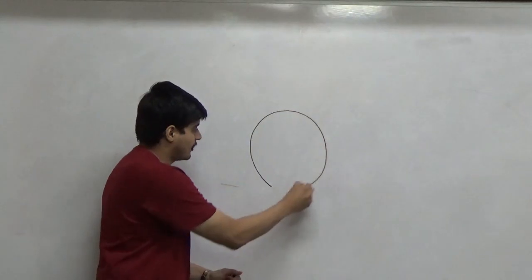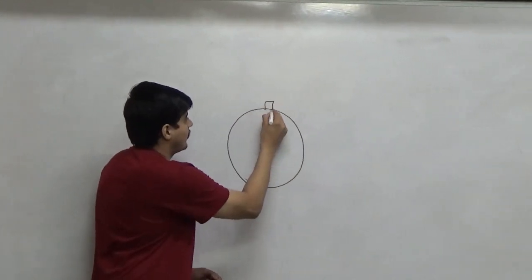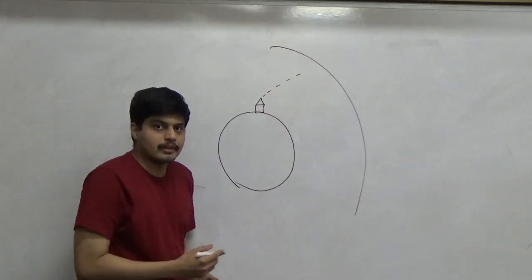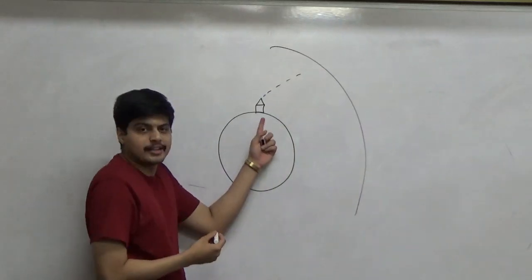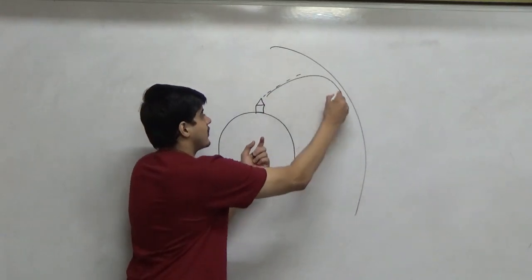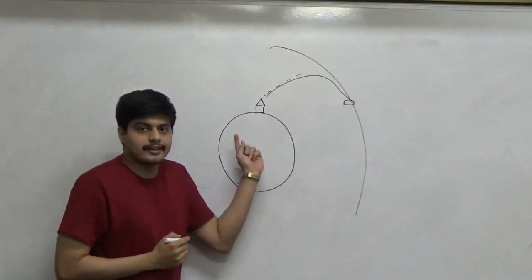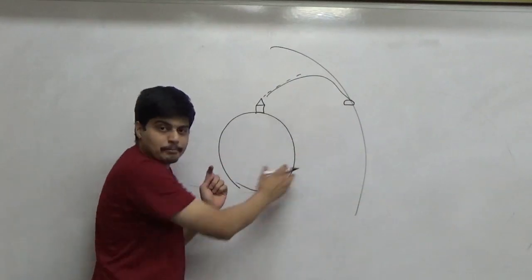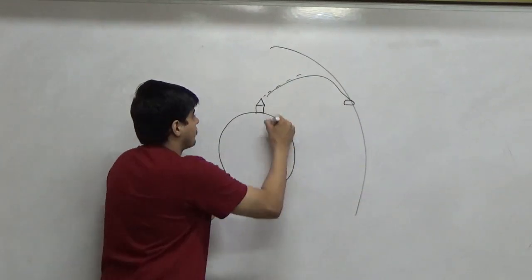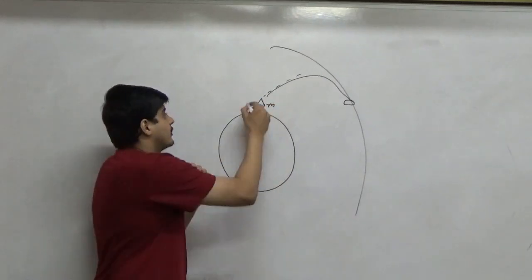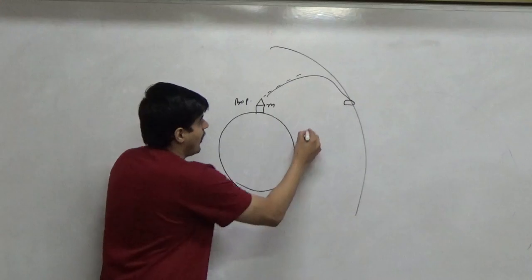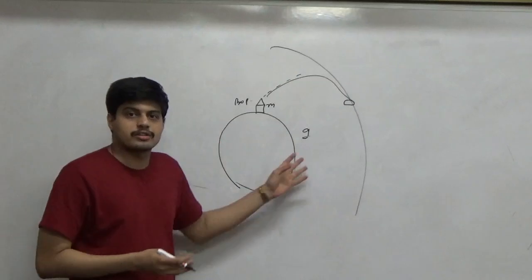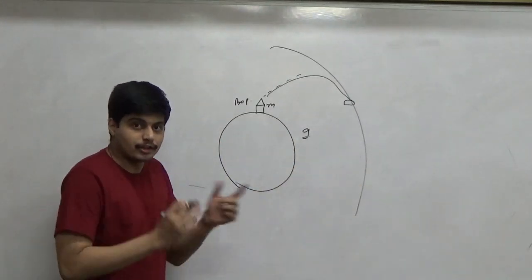So imagine this is the surface of Earth and you have an aircraft which takes off from here and goes to a higher orbit. This spacecraft, from its motion at time t equal to 0 till it settles down in this orbit, is something that spaceflight mechanics is very much interested in. But this entire maneuver is a function of three things: the mass, the propulsion system that drives it, and the gravity. Now this g, the gravitational constant, we have always been assuming this constant for all our calculations so far, is a very notorious thing.